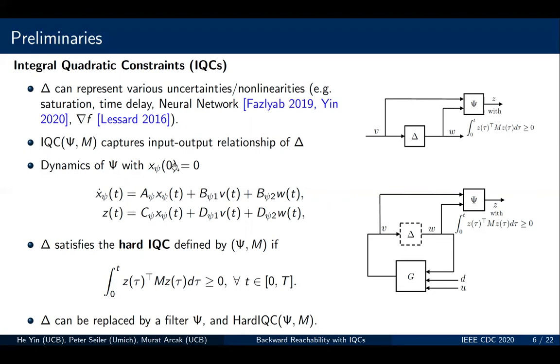We say a perturbation satisfies the hard IQC defined by psi and M if the integral of the quadratic term is non-negative for all time t. In the later analysis, we will replace delta by a filter psi and its corresponding IQC as shown in the figure.